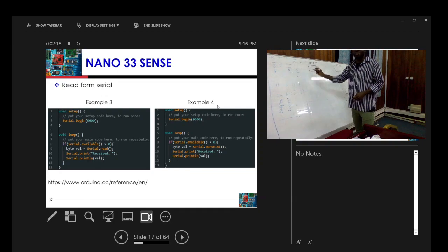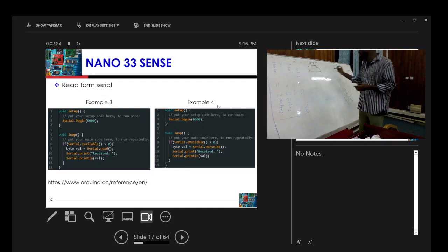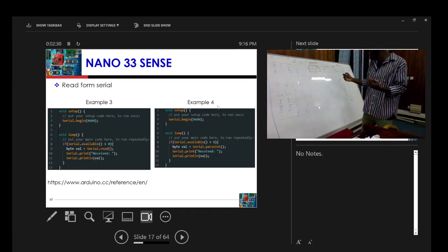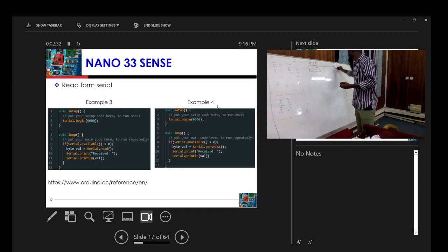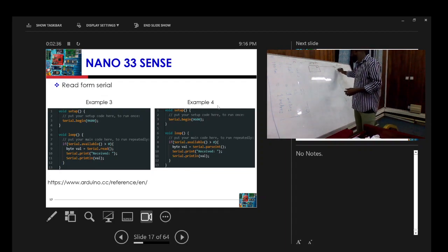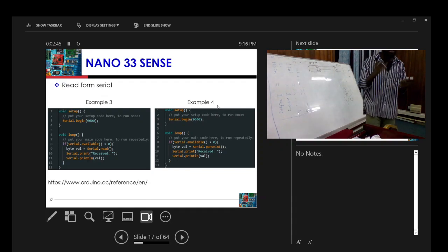So you have the TX, right? The TX means that I can transmit a value or a number through that pin to the board. And then once it gets to the board, it should be able to receive it. So here it will be RX, the receiver of the board. And then I can also transmit from the board, TX, to the computer, and the computer also receives it, RX, right?